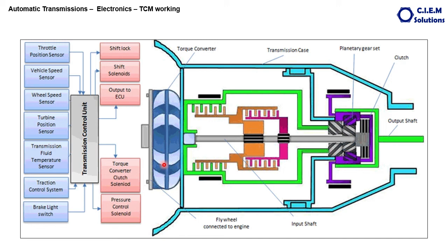Now you engage it, so that the complete torque converter will be rotated as a single unit, with the torque multiplication becoming 0. Then the pressure control solenoid, the main pressure regulator valve, what we discussed in the earlier version. The main pressure is controlled through this solenoid, again taking various parameters. Okay, this is how the inputs to the TCU are processed through the processor and the outputs sent, and finally delivering the desired quantity of fluid at the desired rate to the respective clutches, and also disconnecting the running clutch and engaging the next clutch, for smooth engagement.